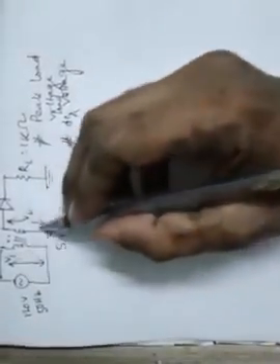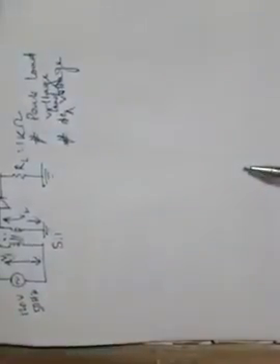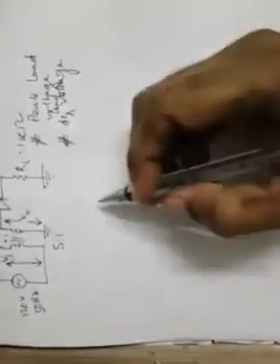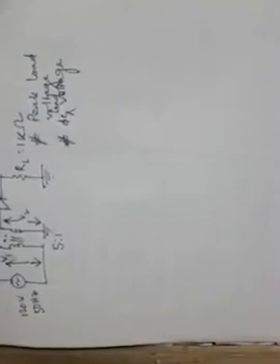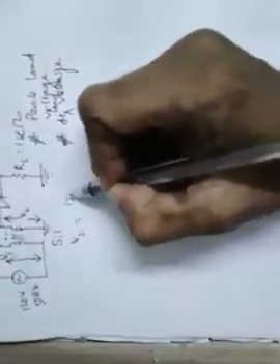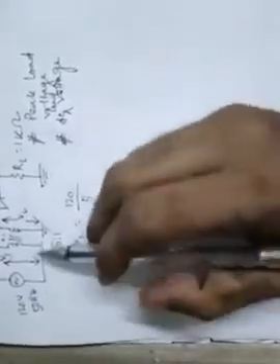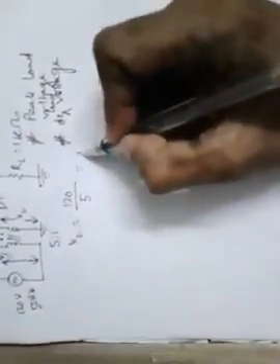So V1 is the peak primary voltage, V2 is the peak secondary voltage, and it is expressed with their RMS values. So we can find V2 as 120, which is V1, divided by 5, because V2 is 5 times less than V1. So that means it is 24 volt.